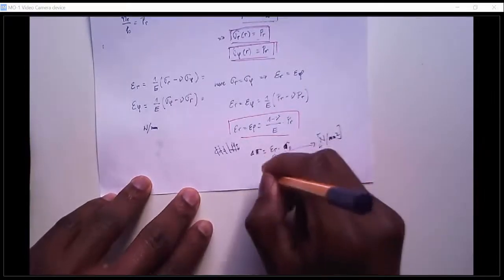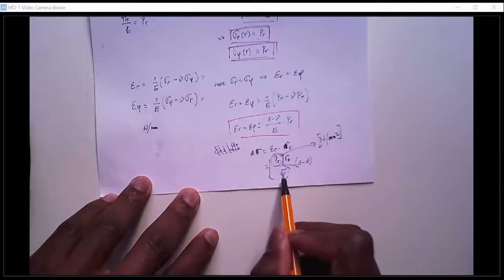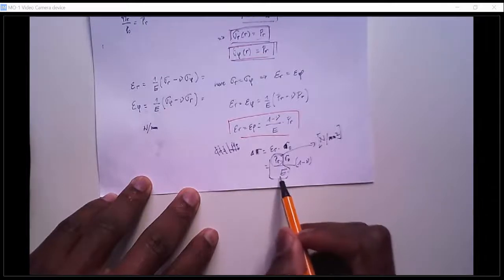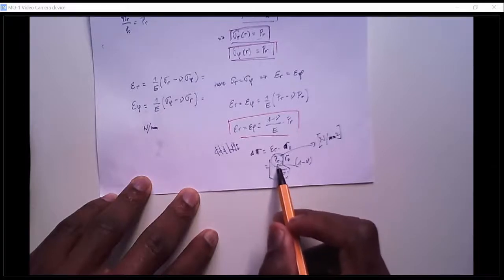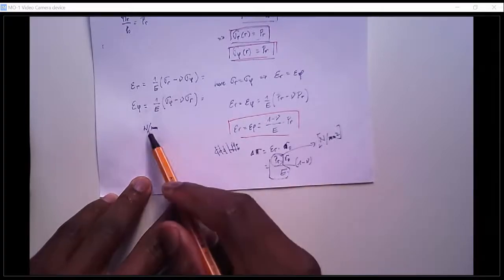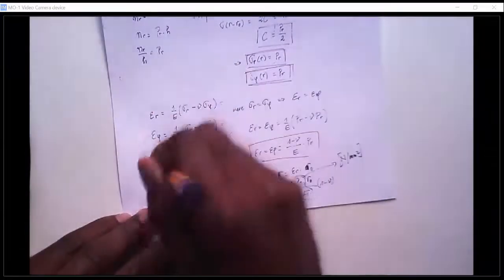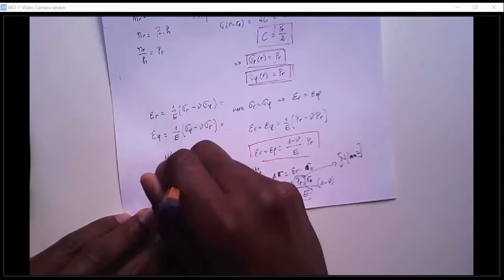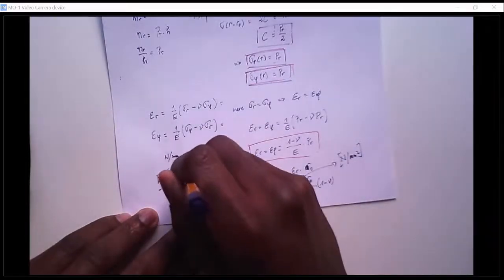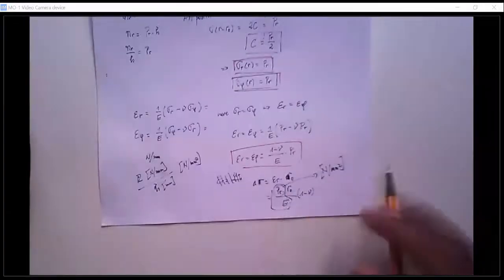Because if we need to have a strain here, then the Young's modulus has the unit Newton per millimeter squared, for example, and on the numerator, we need to have the same unit, Newton per millimeter square, not Newton per millimeter. And that's why they need to divide their value, their R value, that's actually Newton per millimeter, by the thickness in millimeter, for example, so that they get the right unit, Newton per millimeter square, for the formula. So this is basically correct, what we've done here.